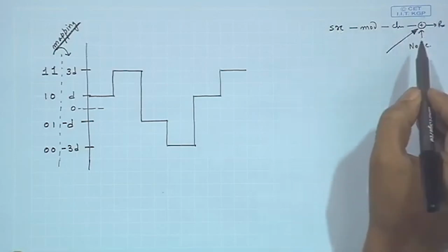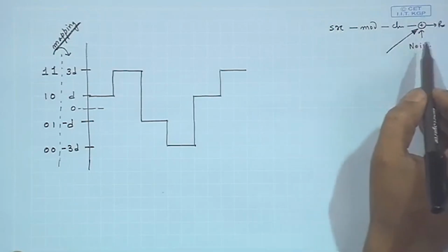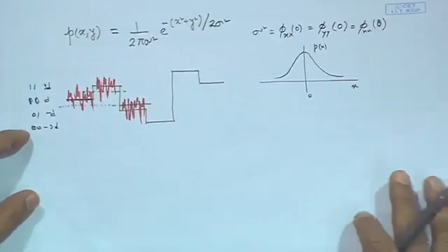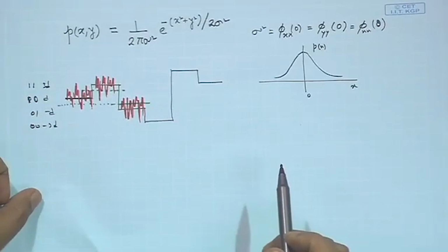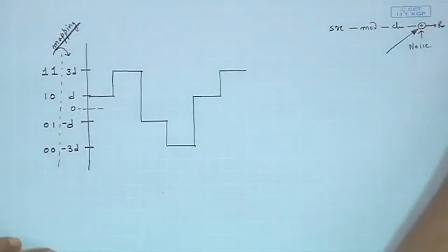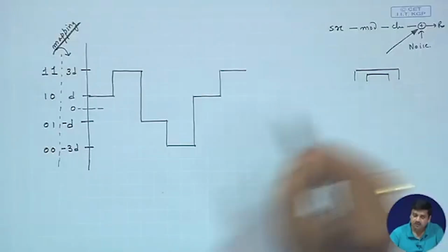And we said it is Gaussian because of the probability density function of noise that we described in the previous lecture, and we said it is white, and the spectral properties we did discuss. At that point we said that you can think of a narrow band white stochastic process in the sense that I have a filter which is wide enough to pass my signal.